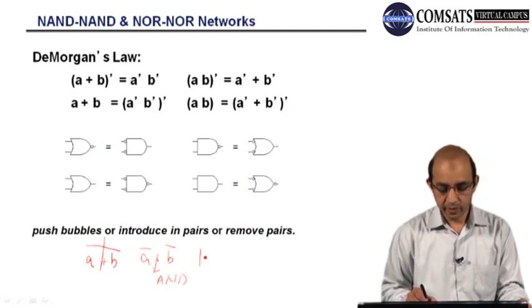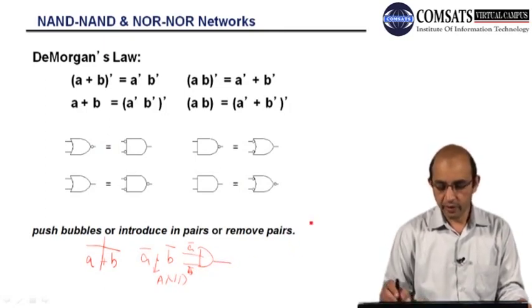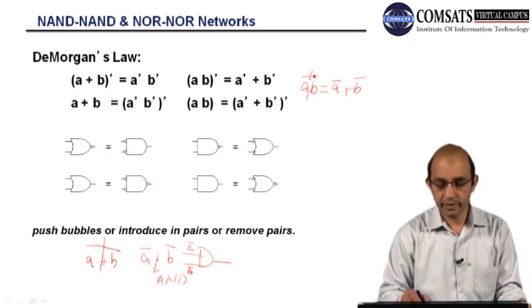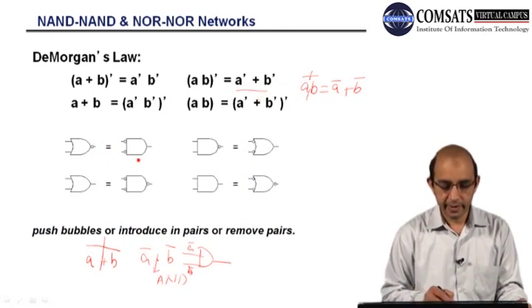So if I have to represent it symbolically, these are the complemented inputs, B bar, and this is the AND gate. Similarly, whenever we have to represent AB whole bar, what we will be having? Break the line and change the sign. So we will have A bar ORed with B bar. So this is the same, we have A bar plus B bar.